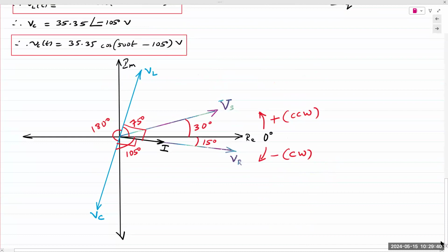In this case, let's take a look at voltage Vs. What do we need? You simply take the phase angle first, and we draw a line approximately at that angle. And that's it. Mark the angle and note down the length. It's not to scale. Okay. So Vs is 100 volts with an angle of 30. So approximately draw out 30 degrees, draw a vector, and mark it as Vs. And again, as I stated, this is not to scale.